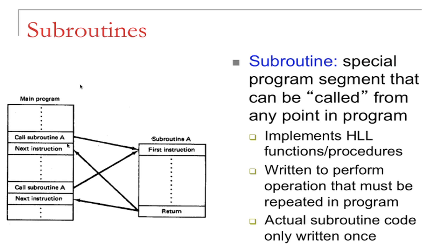So why do we need to have this call and return? Let's see, if we have this kind of jump instructions here, also here. Let's see what will happen when we make that jump second time. So when we replace this call subroutine A with the jump A, we will have the microprocessor continue its execution from the first instruction of this subroutine.